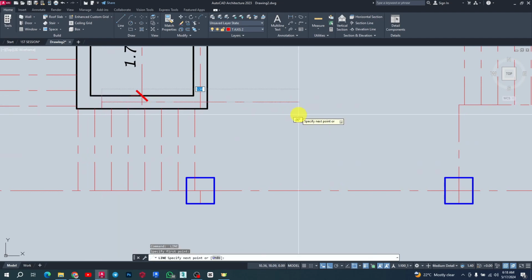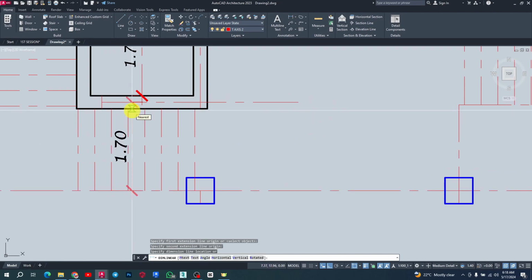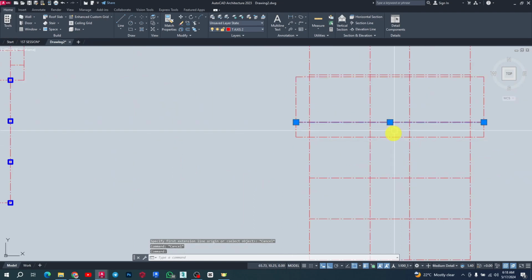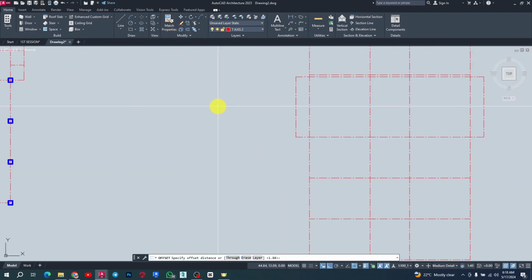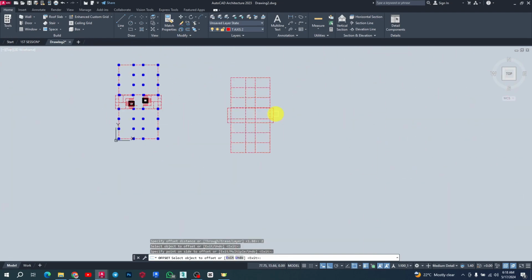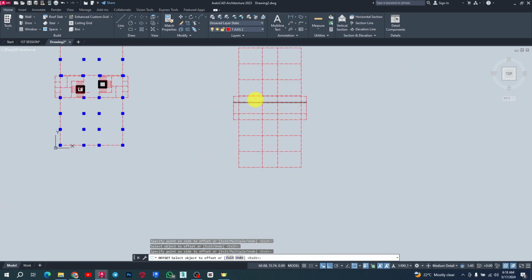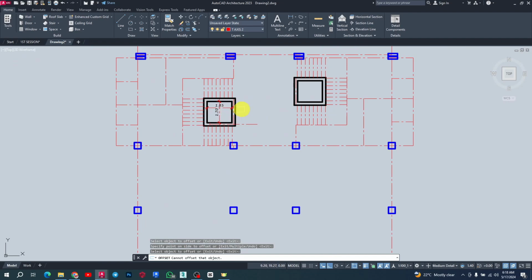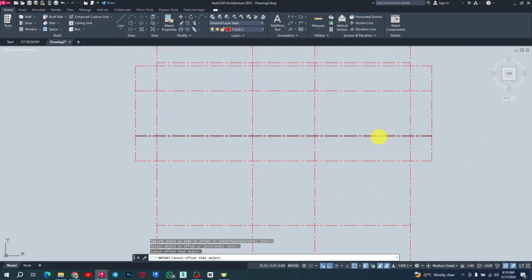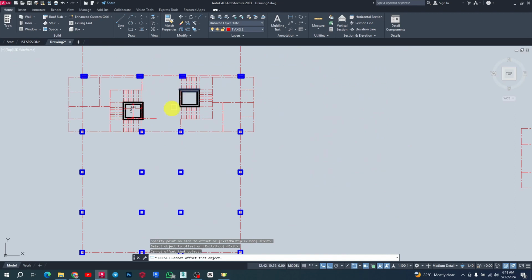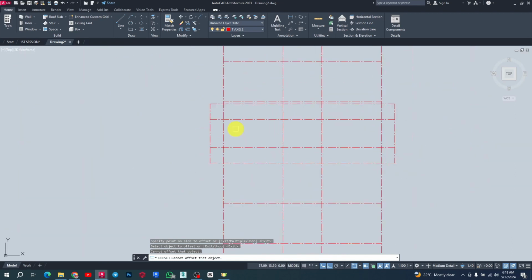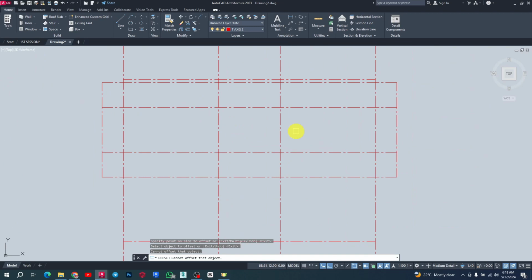Okay, so this is the center line. From here to here is 1.70. We're adding 0.3 there, so it means from here to there is going to be 2 meters. I was supposed to just take 2 meters anyway, so that I have the wall acting there. I have 2 meters here. Since they are both from different directions, I'm going to have the same 2 meters this way, so we don't have both of the lifters facing each other directly. That is one of the reasons why you see them not really facing each other. You can climb in either direction. That is something to check out. It's just for traffic reasons.